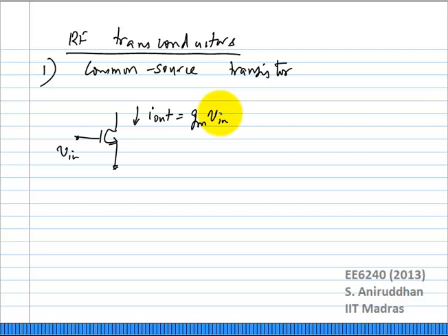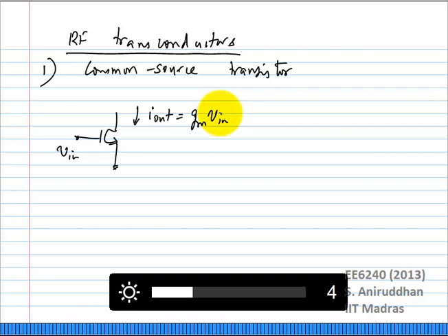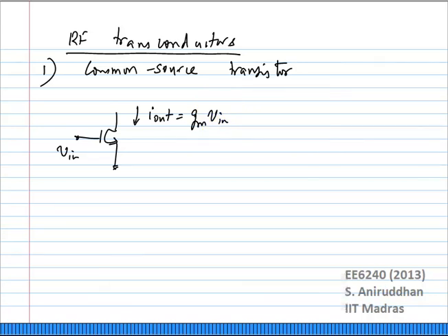But apart from that, how would you characterize the linearity of the mixer? We have seen it's through IIP2, IIP3 and so on, right? So let us take the case of a super heterodyne receiver where we are interested in IIP3. So what parameter are you interested in as far as this MOSFET is concerned? Gm gives you the conversion gain. What aspect decides the linearity of this device? The resistance.